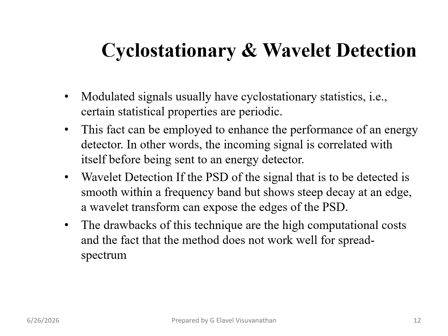Next, cyclostationary and wavelet detection. Modulated signals usually have cyclostationary statistics, that is, certain statistical properties are periodic. These facts can be employed to enhance the performance of an energy detector.